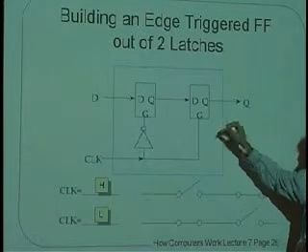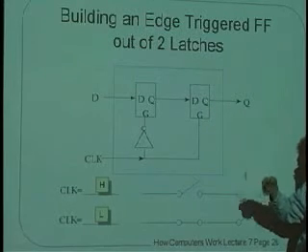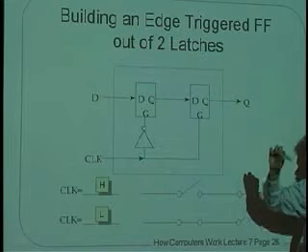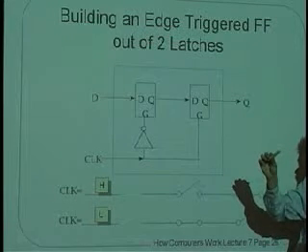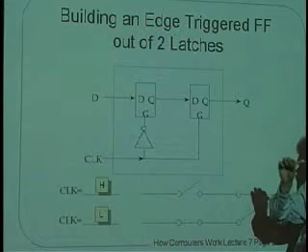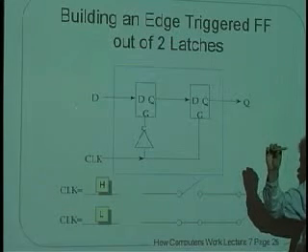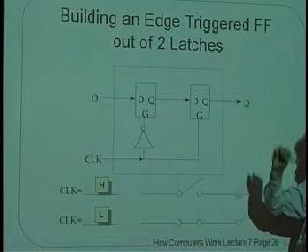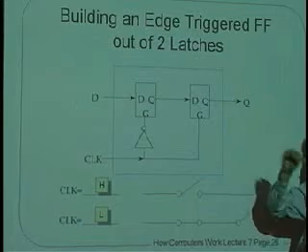A selector is not a memory element. So when you're halfway between one switch setting and the other, it doesn't know what to output. So what we're saying is that if you are halfway in between the two settings and both of the inputs are the same, output whatever that input is.